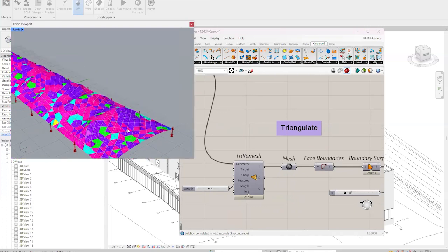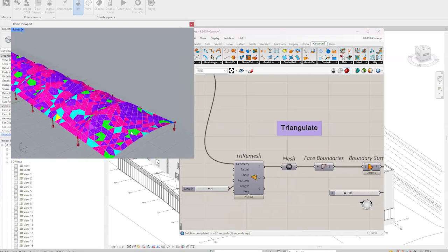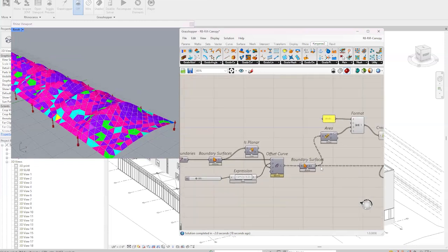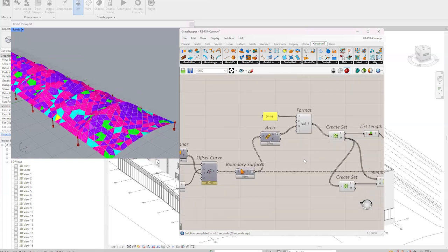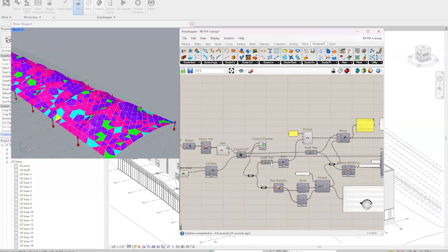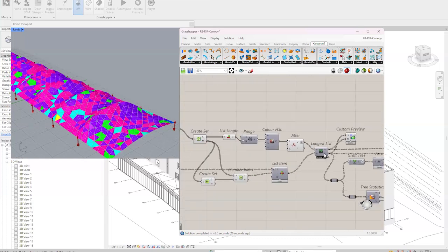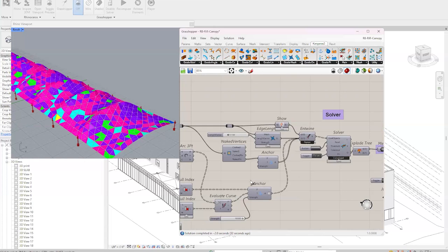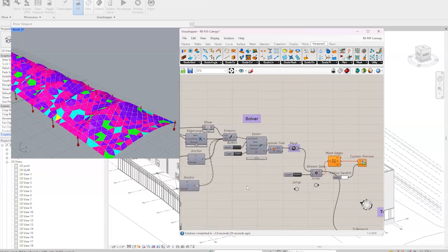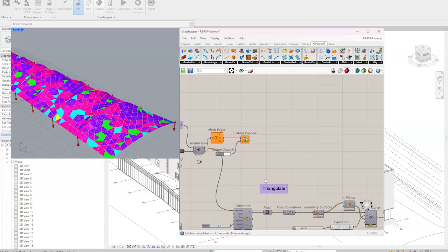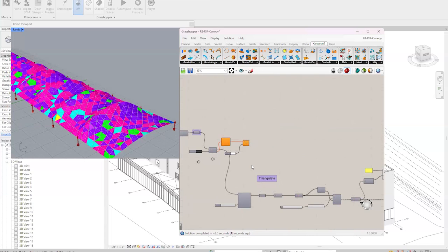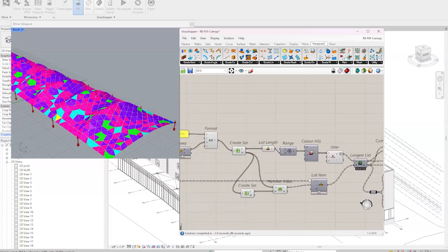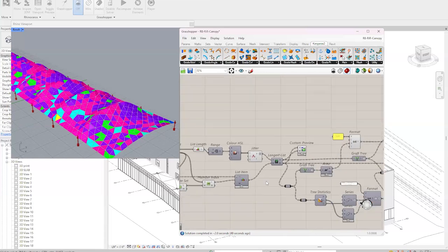We're doing a panelization of, in this case, triangles, because they're planar and a little easier to manufacture. This could be anything though. We're colorizing them per size, so they're optimized by Kangaroo for a certain length, but it's only going into a certain amount of optimization. This way, for the fabricator, each color is just a unique size. The fabricator might say, okay, just keep it under 10 different sizes, and there won't be any additional setup cost to manufacture.